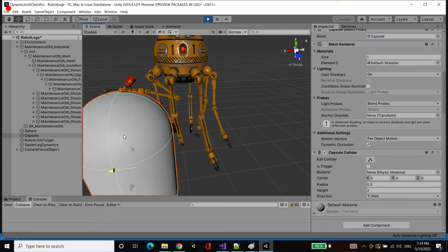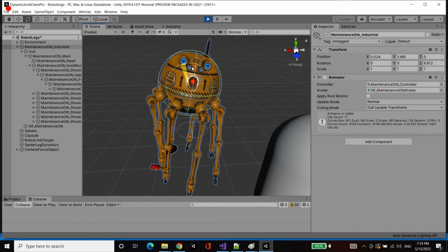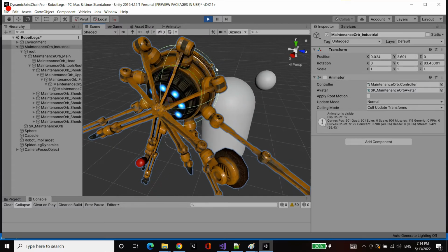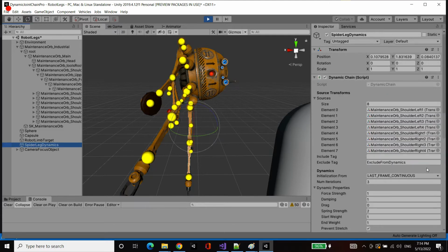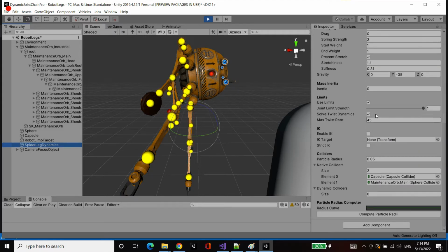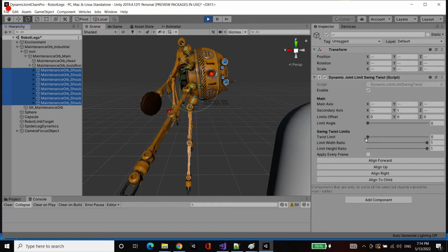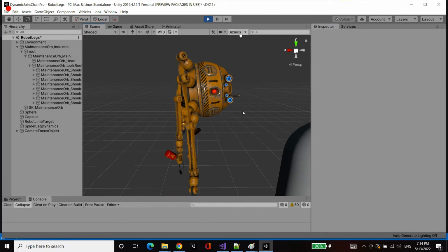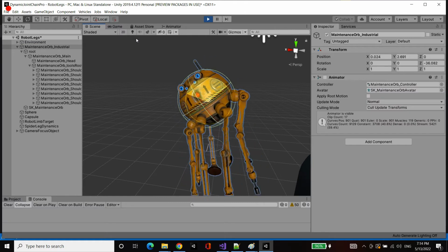And you'll notice because I've got the shoulders completely clamped, we can't solve for twist at all. What that also means is if I rotate the system as such, then because we don't have any range for twist, we can't bring the legs of this robot downwards. However, if I go into my dynamic system and I select the shoulders of the legs or the roots of the legs and I increase that twist limit, what you're going to notice is because of that increased range of motion for twist, finally I can actually apply twist to solve for the dynamics as well.